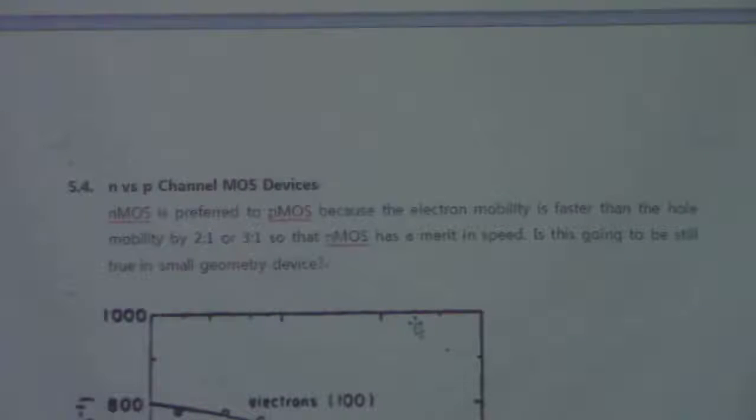In this substrate resistivity selection, if you want to make a small device, you have to have a substrate resistivity of more than 10 ohm centimeter. Typically, this is going to be 20 ohm centimeter. And the threshold voltage becomes 0, so you have to do some ion implantation to control the threshold voltage. That's what we have discussed in this section. Okay?